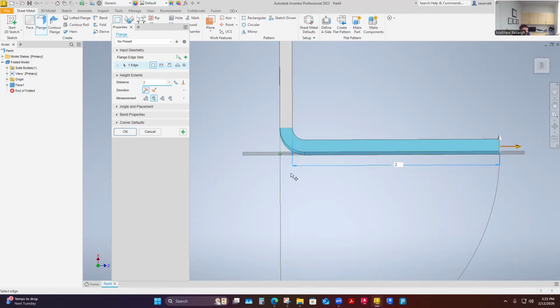That's what can break materials that aren't designed to do this. The material can't handle those compressive forces, and then you have a bend that breaks. Some materials are bendable, but we can still end up breaking them, and there are some relief cuts that we can do to help prevent some of that breakage, even on bendable material.